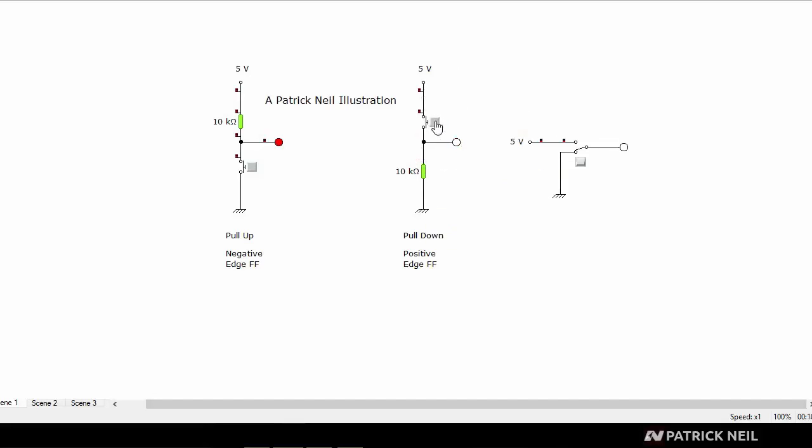So you are creating a digital signal here because you are using one wire to switch from high to low, which is actually called a pulse, or when you have a stream of them, which is just a bunch of high-low, then it's called a clock signal. If it wasn't for these pull-up and pull-down circuits, this is the way it would have to be done. This pin goes to positive power, this pin goes to ground, and then we will use a single pole double throw switch to switch the output between either high or low, just like that.